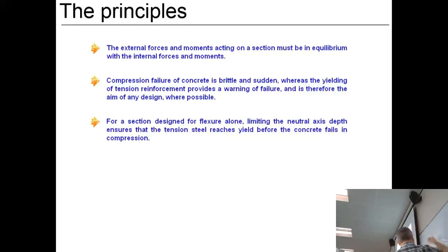So you'll find that we'll start looking at the force in concrete, and we'll look at the forces in steel. And the force in steel stays the same, because you find that the stress of the steel is 500, though the design stress is 435. So that's kind of set.